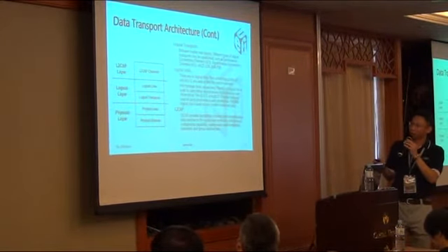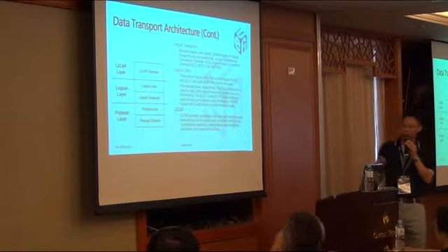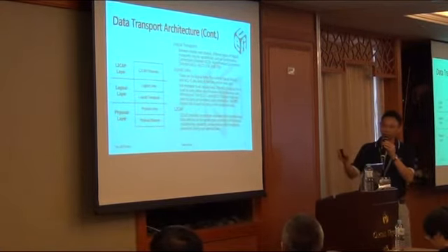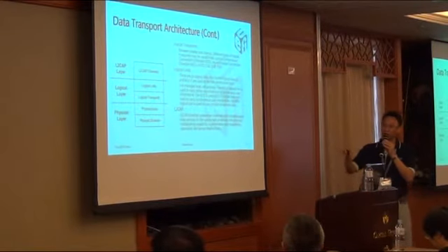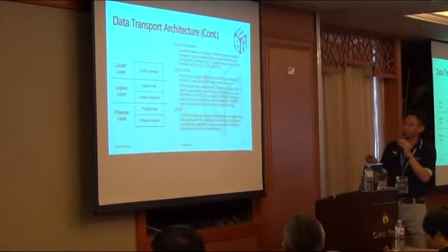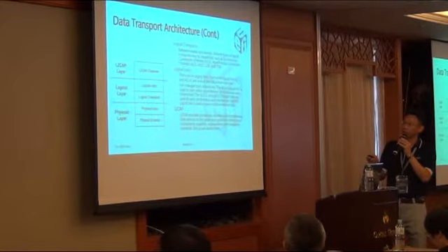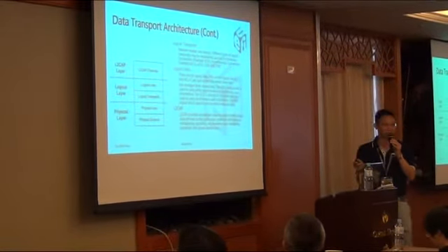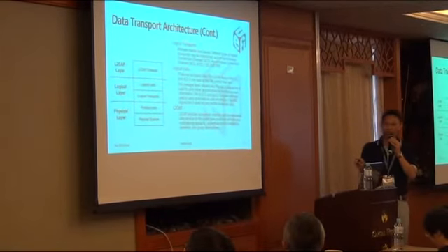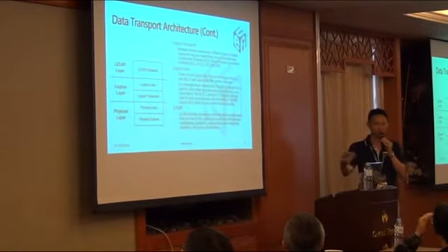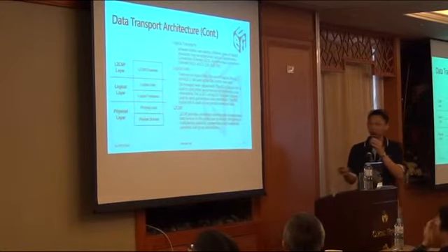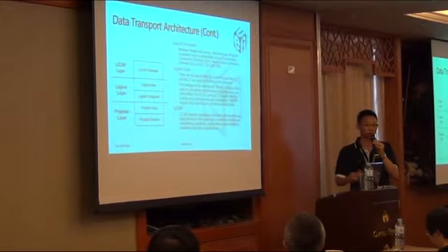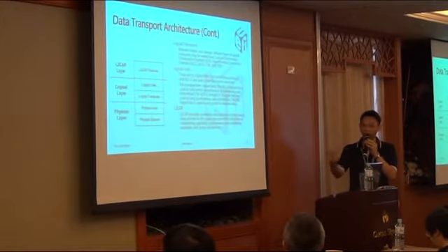There is the logical transport. The logical transport carries the logical data packets. In a future slide, we'll explain the data packet format. For now you just need to know that Bluetooth supports synchronous transfer and also asynchronous transfer. In USB terms, it's like isochronous transfer or asynchronous transfer. Synchronous is for audio, and asynchronous is for control or data transfer with integrity guarantee.